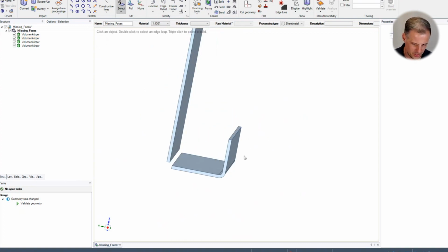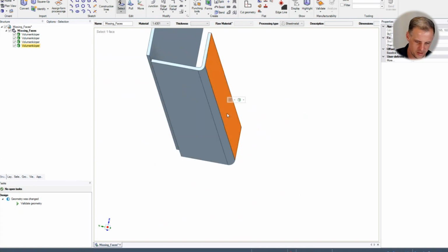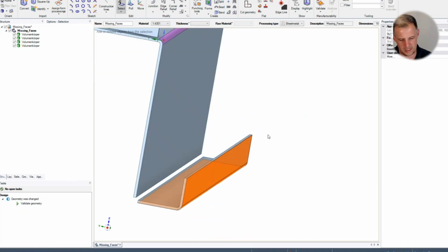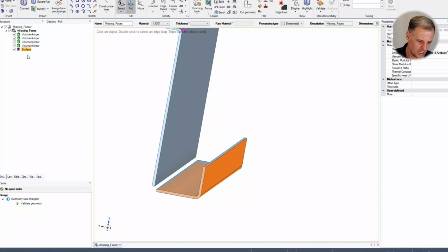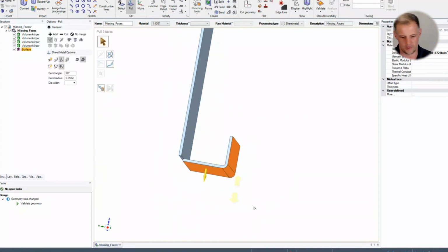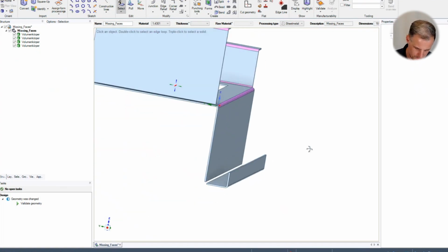Also here it can be possible, or if this conversion does not happen, remember, double click one face, copy, paste, and you will get this face, which then can be thickened up in the right direction with the thickness, and it will lead to a valid solid in this case. So just let me delete the face. I think that's clear.